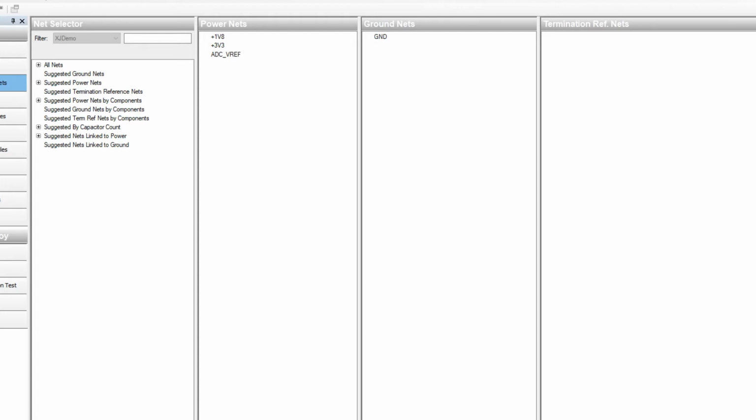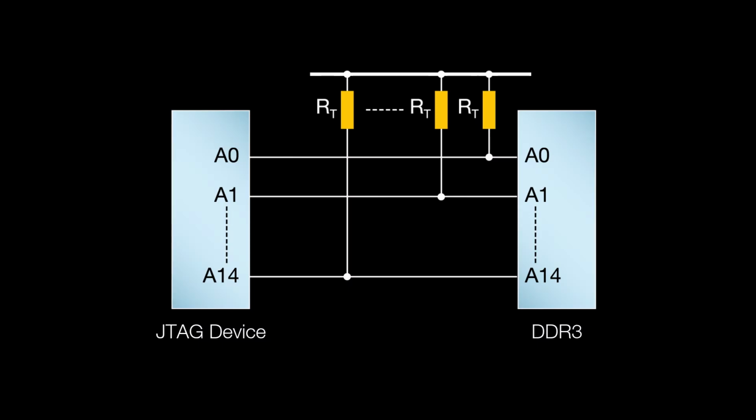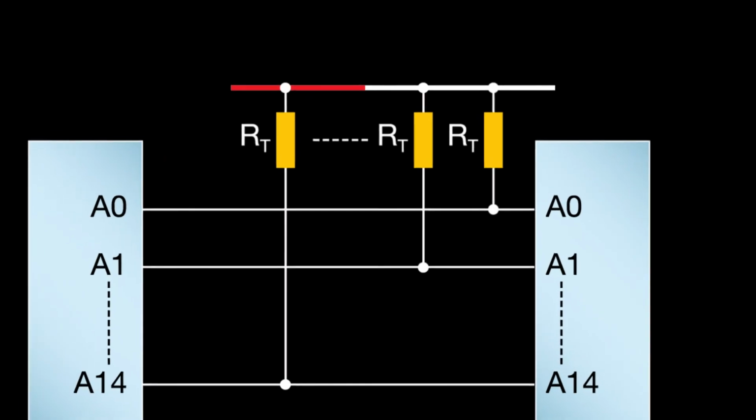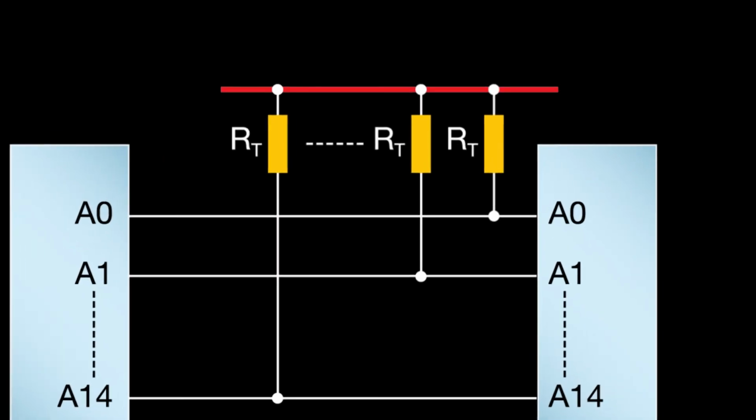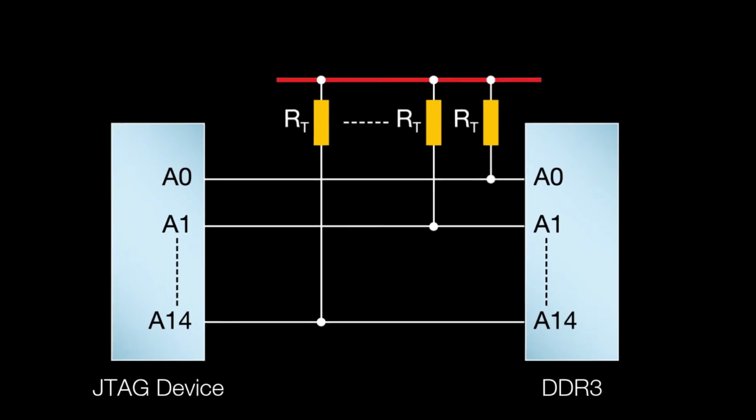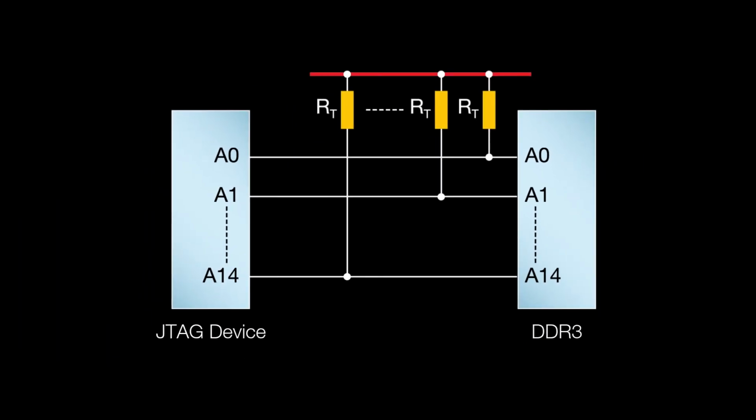As you can see, there were no termination voltages in this circuit. They are often used with DDR memories to provide the mid-rail supplies needed for the termination resistors. I'll talk about those in the 3rd video of this series, so be sure to watch that if you've got that type of supply rail in your circuit.